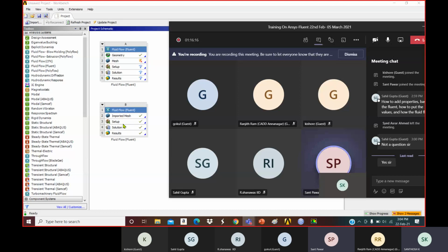Okay. And is there any criteria for quality of elements, as we have in HyperMesh? Yes. Aspect ratio, Jacobian ratio, skewness, all that you should be aware of. In Fluent we are not going to discuss that. If you want, in Ansys Workbench and HyperMesh we are going to teach you that. People who know HyperMesh should be aware of aspect ratio, minimum size, maximum size, warpage. Then only can you understand.